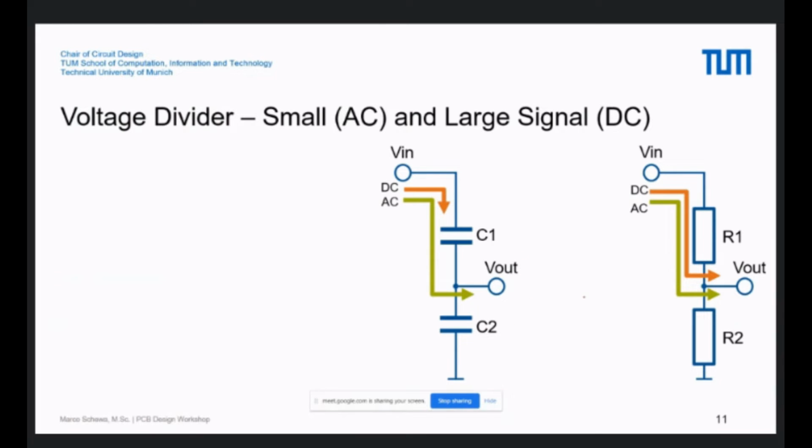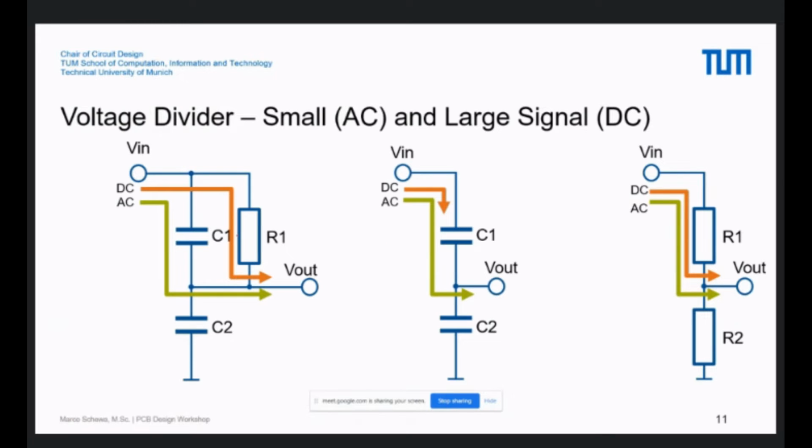So it means if you have your op-amp here, the operating point is destroyed. Therefore, you can put an easy resistance here to feed the output with the DC. So here you have an AC voltage divider with only C1 and C2 if R1 is very high, and you have the DC feed here. But the DC is not divided, so only the AC is divided.